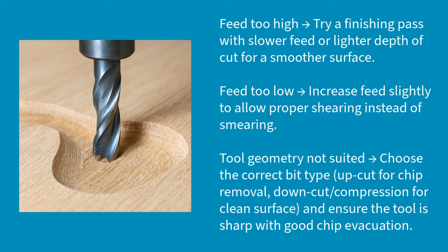Another thing I'll mention is just that, as you're changing these parameters, say you're seeing poor chip quality, you want to change these parameters and then test and then see if it's working and then change them systematically. You don't want to change 3 at once because then it might fix it, but you might see a different problem, but you don't know what you changed. So change it systematically.